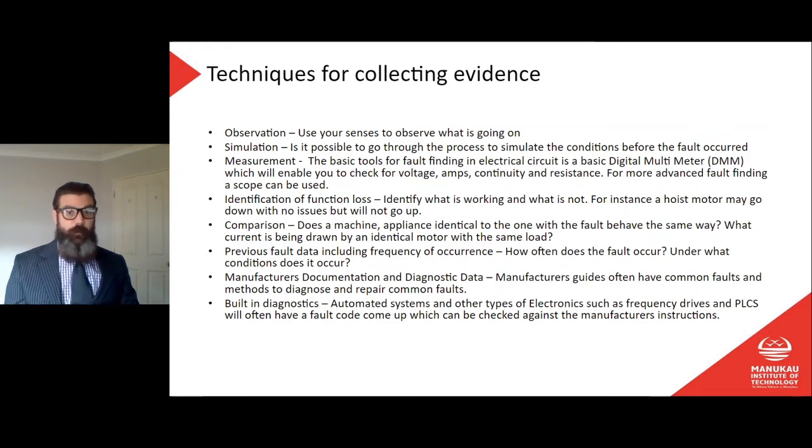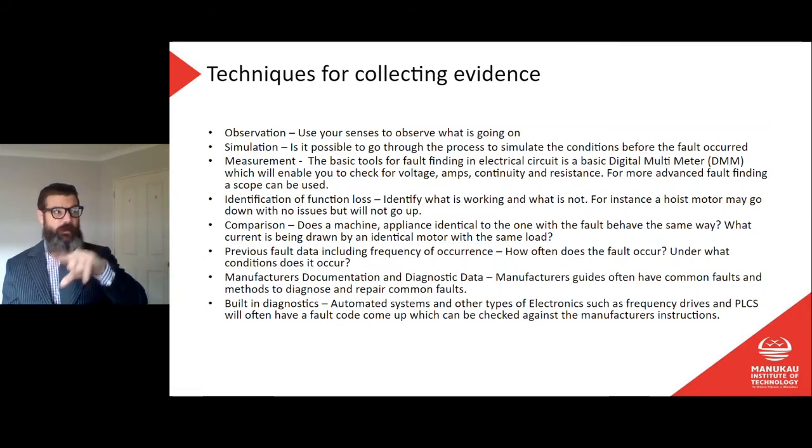So if a pump loses its program, if you don't have that written down, sometimes that can be quite difficult. But I could go to the pump next to it and go, what's the programming in this one? And then usually work out from there what I need to do for the one that I'm working on.